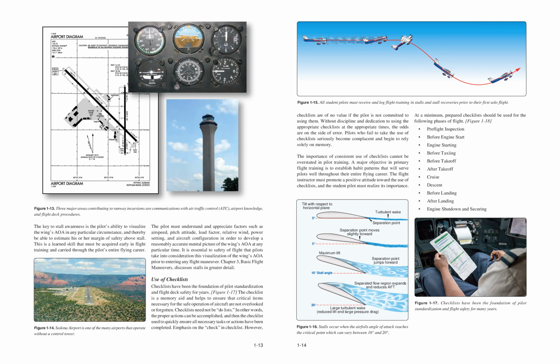Figure 113. Three major areas contributing to runway incursions are communications with air traffic control (ATC), airport knowledge, and flight deck procedures. The key to stall awareness is the pilot's ability to visualize the wing's AOA in any particular circumstance, and thereby be able to estimate his or her margin of safety above stall. This is a learned skill that must be acquired early in flight training and carried through the pilot's entire flying career. Figure 114. Sedona Airport is one of the many airports that operate without a control tower.